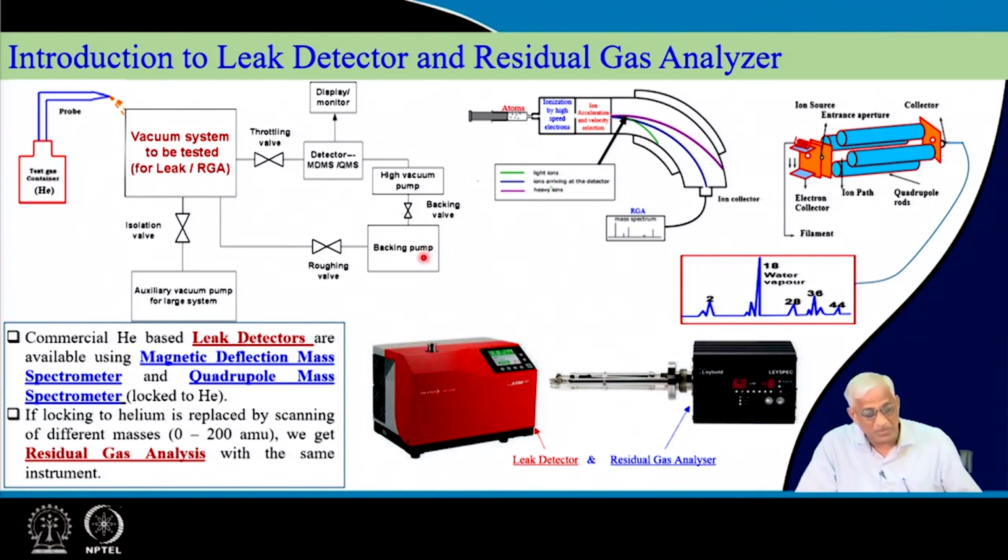And this backing pump, which was originally the backing of the detector vacuum pump, can also be used to evacuate if this volume is smaller, because the vacuum pumping system attached to the detector is relatively small, but high vacuum. It also has a turbomolecular pump and a backing dry pump or rotary pump, but capacities are not much. Its purpose is to keep the detector in good vacuum condition, but you can use this to rough it, provided the system is small.